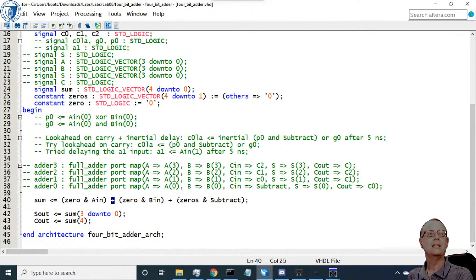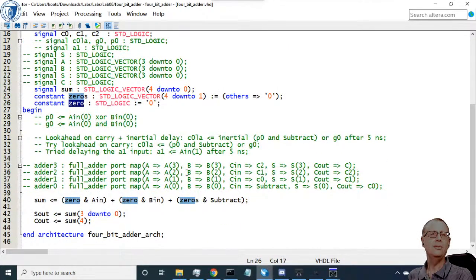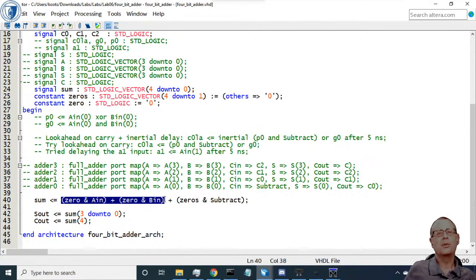Right, and then I decided I've got an internal signal which is a 5-bit number, and I've got a couple of 0 vectors, and I just take my 2 inputs and I concatenate them with a most significant bit 0 vector.